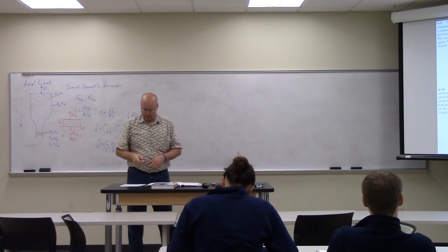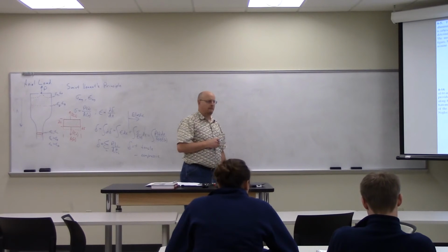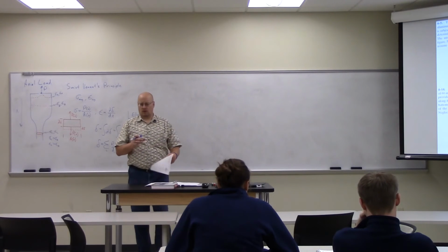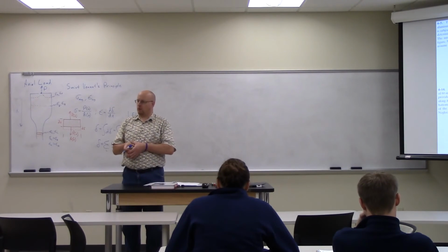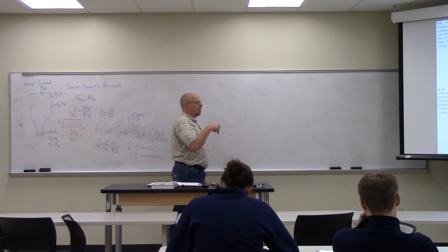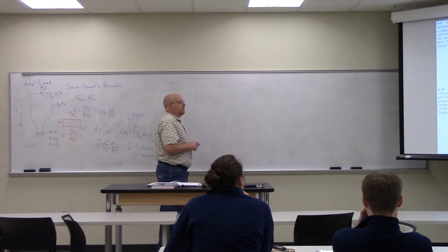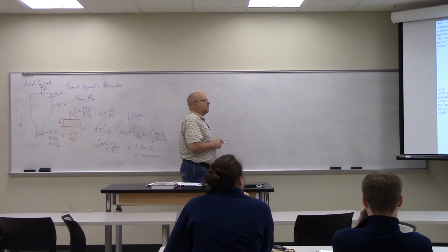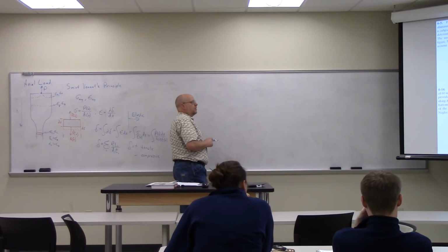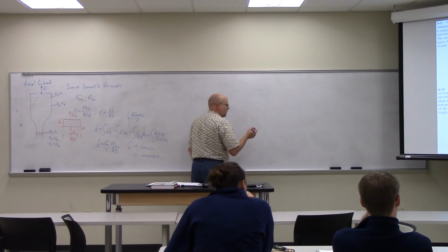Okay, 414. We have a Douglas fir post buried in the ground, and it has a diameter of 60 millimeters. So it's roughly a 2.5 inch diameter post. It is subjected to a compressive load of 20 kilonewtons, and the soil provides a frictional resistance uniformly distributed along its side of 4 kilonewtons per meter. Determine the force F at its bottom needed for equilibrium, and also find the displacement of the top of the post with respect to its bottom B. We can neglect the weight of the post.